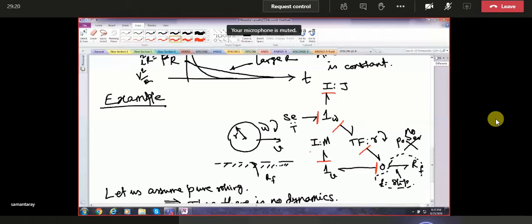What we can see here is originally the system had 2 degrees of freedom. If that friction there was slip, the system has 2 degrees of freedom. If this resistance was present, then we can give this one also integral causality and change the causality of that. That RF is there, we can adjust the causality with RF.